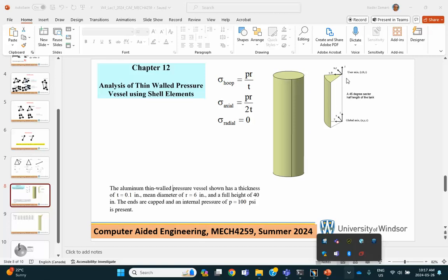But if, just hypothetically, you did an arc and revolved it to get this top surface, and a vertical line and revolved it to get the side surface, these two surfaces will not talk to each other. So when you mesh them, you have to do them separately, and put properties on them separately. Even then, they may look okay, but the nodes on the top and the side do not talk to each other.